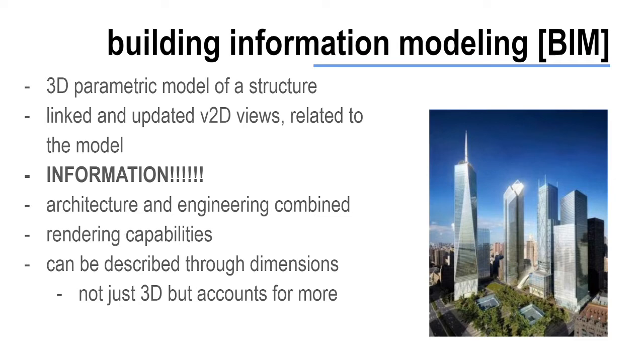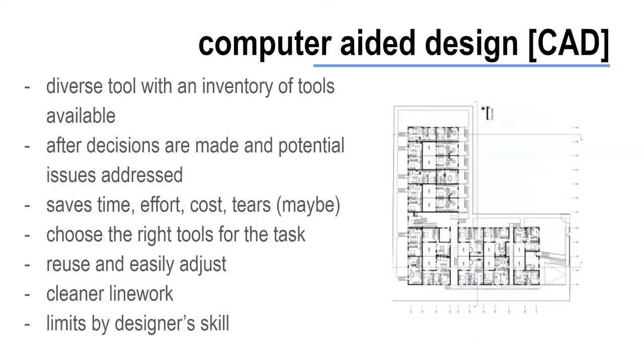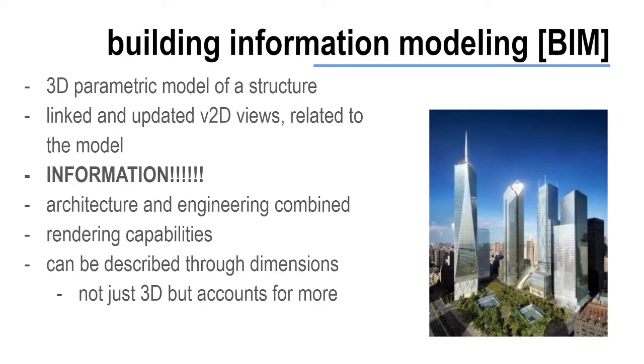And so what could easily get out of sync in AutoCAD, remember, if I had to add on 4 more rooms over here, I have to then update all of the side views, the foundation, the electrical, all of those. It could be easy for me to forget to update one of those views. Well, with a BIM model, everything's done automatically. So if I make a change in the floor plan, it updates the whole 3D model and changes any of those other related views.